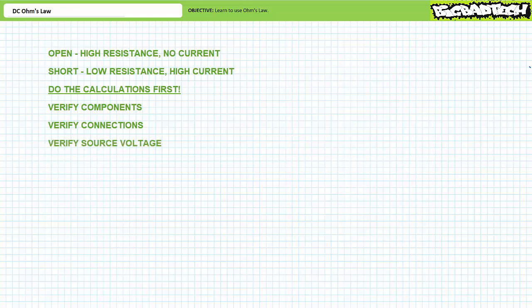Supply your circuit with the correct voltage. Verify output voltage before and after you hook it up to your circuit. Use your DMM to check it. If you're going to use your DMM, use it properly. We already covered the ohm meter in a previous lecture. We'll go into details about voltmeters and ammeters real soon, but recall the basics.